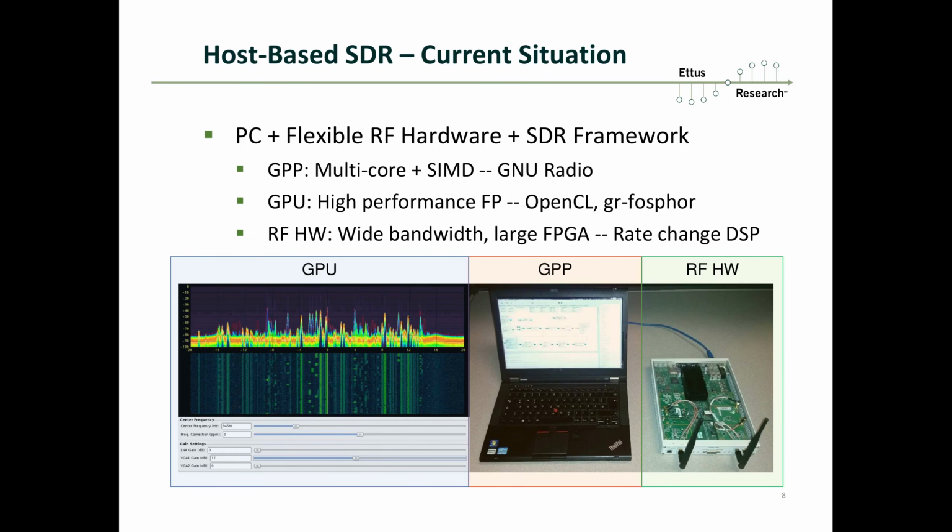Increasingly, applications are using the FPGA to accelerate processing. The FPGA is attractive for several reasons. First, it provides dedicated hardware resources, so it is capable of handling especially high data streams, supporting very wide bandwidths. Second, it is also well positioned in the signal chain, being close to the antenna and data converters, closer than the GPU, and does not necessarily require support from the CPU to operate. These features make the FPGA ideal for many operations, such as sample rate conversion, filtering, and channelization.